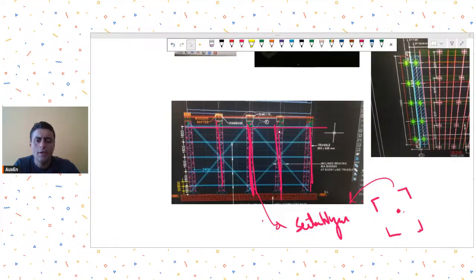So I'll recommend that before you take up something like this, first understand some basics of steel design and try to get some report on this type of shuttering design from somewhere. You will understand how that trestle system is provided first of all, and then how the calculations need to be done.